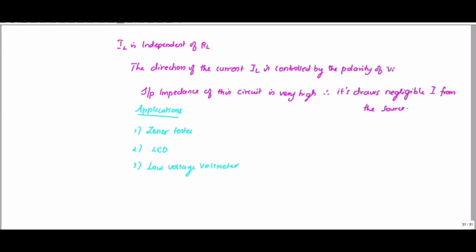We have to make sure that while designing the RL and RF, the values are not very small. Otherwise the output current becomes high, and this pushes the op-amp to saturation.